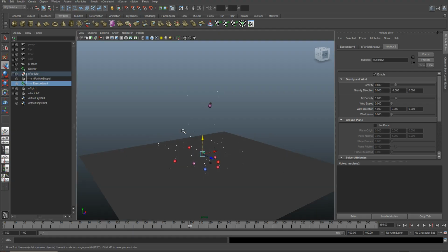We also need these particles to die at some point. So in the next part, we're going to come back and solve both of those problems. We're going to dive into a little bit of MEL scripting for controlling emission rates per particle, and make this look a bit more like we want it. We're going to use an acceleration ramp to control the secondary emitted particles also. So I hope this has been understandable and easy enough for you, and I'll see you in the next part.